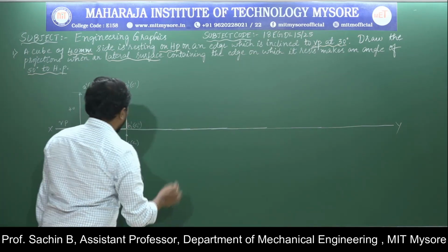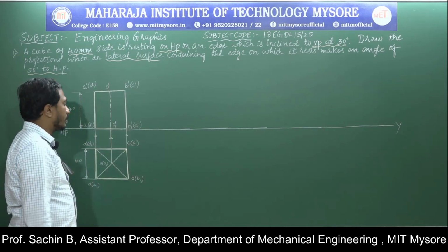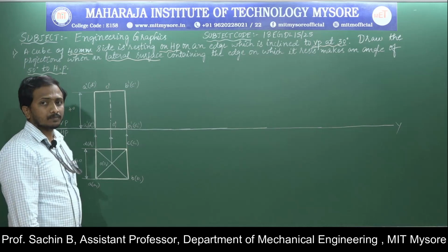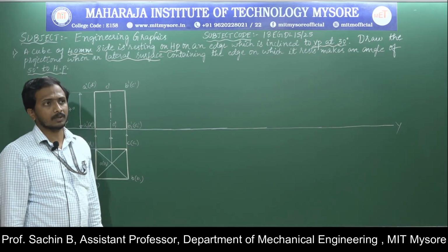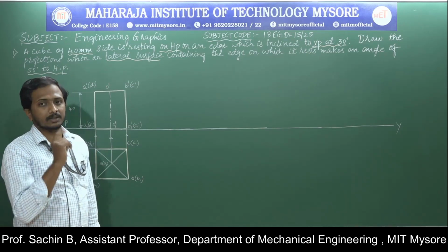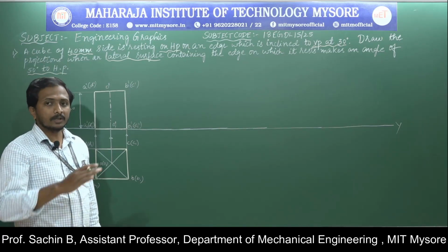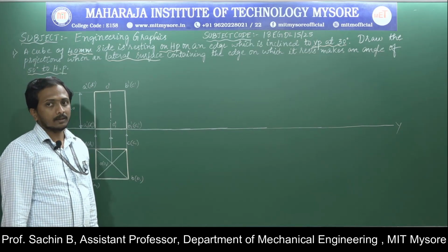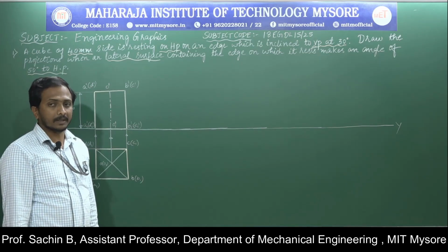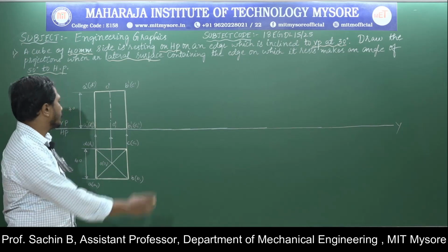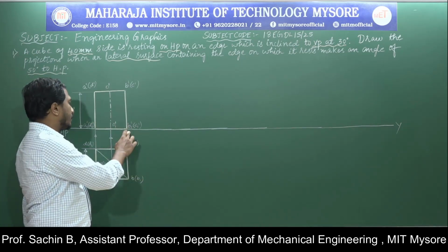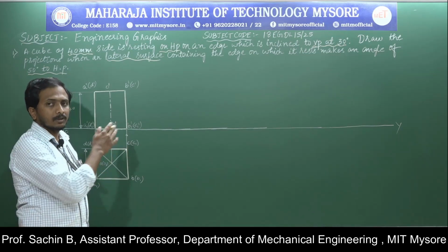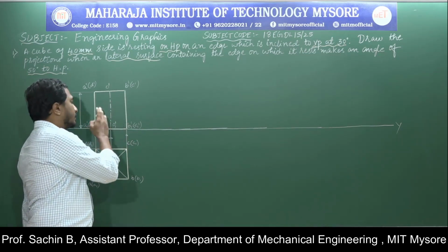By knowing that, I am going to rotate the object towards my right at an angle of 50 degree. But in the pyramid problems you know the concept that if the axis inclination is given in the second position, you rotate the base first by subtracting the given angle from 90 degree. Here the lateral surface containing that edge is parallel to the axis, so there is no need of subtracting the angle because both the lines are parallel.